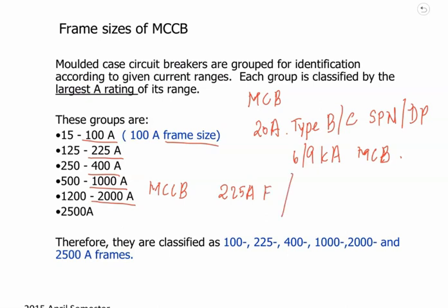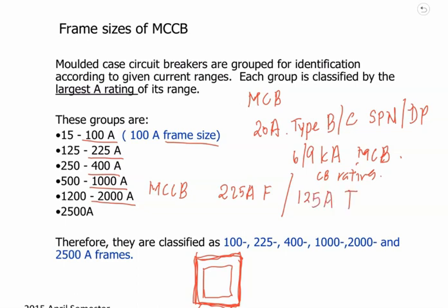After you choose this outer frame, this frame will denote the amount of size and space you have. You can choose the internal unit that comes with your circuit breaker rating. So in a 225 amp frame, for example, you can have a 150 amp trip breaker.